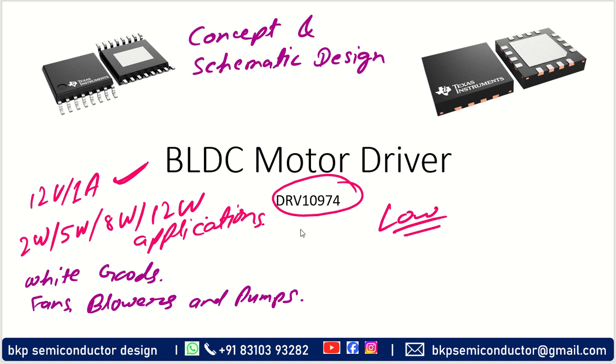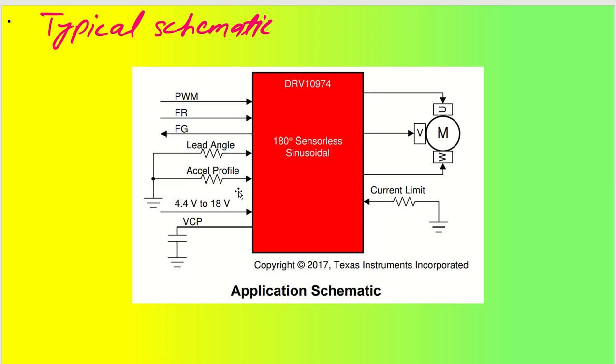Okay. So first, let us try to understand from a typical schematic diagram what are the things we need to set up, right? So let us say we have one IC which is a BLDC motor driver. Now what we need to do in this particular IC is give one supply voltage, which will be, let us say, 4.4 volt to 18 volt rating it has given. So you can give, let us say, 9 volt or maybe 12 volt. I am preferring 12 volt because it is generally available. So 12 volt will be given as the supply voltage.